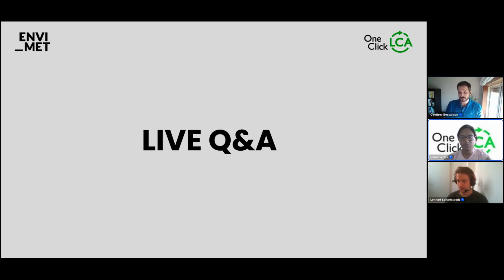All right. Thank you, Geoffrey. And the next question is how the software takes into consideration the impact of paving materials and colors. That is pavers. So we have a database of different materials that you can use for a surface, and these materials have physical properties to them. They have a value for reflection, a value for absorption and transmission, and based on these values, the calculations are being done. So if you have a lighter color, you have more reflection of a surface, and on the basis of that, the calculations will proceed.